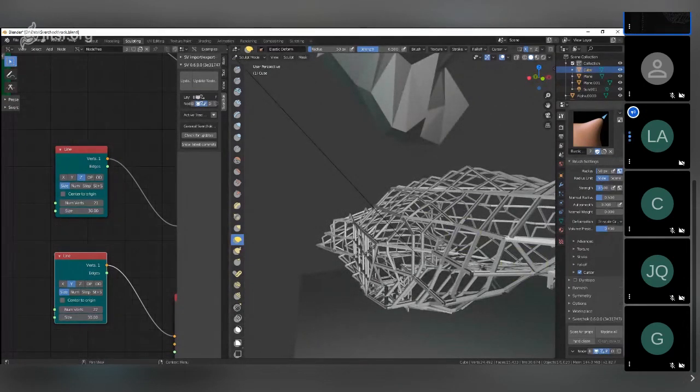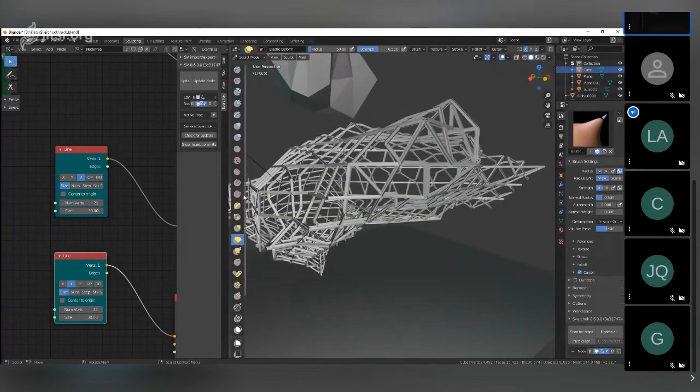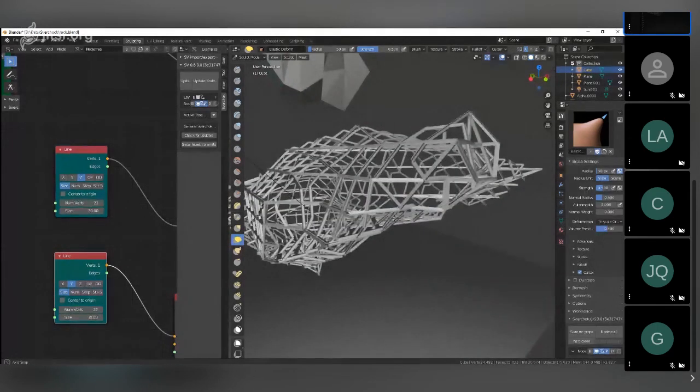Is it calculating some physical properties? No, not stability. I'd export it as a line model and then do some analysis on it. Is exporting in line mode straightforward? Yeah. It was hard to model it as I-sections, but it would be much easier to do it as lines, and then I could export the lines as DXF and then import that into analysis. Okay, that's all I've got to show. I've got some other things I've been doing, but I don't have anything that's showable.